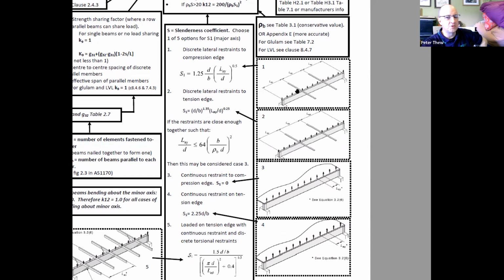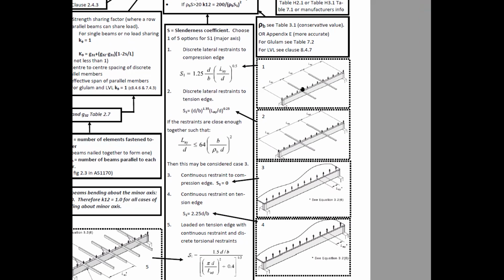You talked about discrete restraints. Can you say the problem again? I'll try and find it. The beam itself is glulam. There's a beam on a roof span that's got a plyboard floor on top. The beam's 6 meters long with 1 discrete restraint in the middle.